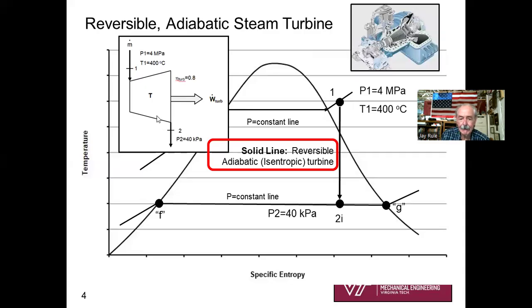And so the assignment could be: determine W dot over m dot, since neither are given, find little w of the turbine. I also need to tell you that this turbine is reversible and adiabatic. Adiabatic, fully insulated, reversible. That means there's no unrestrained expansion in this turbine.